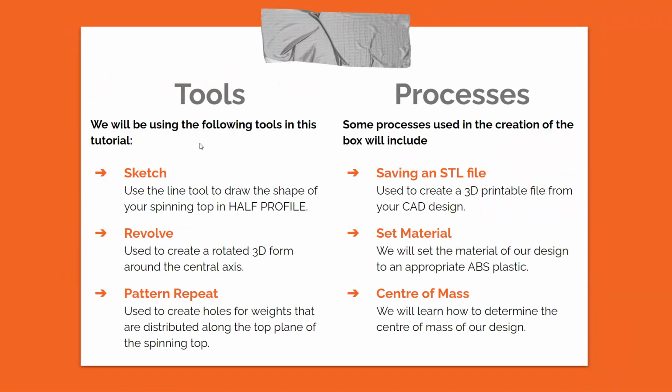So the tools we'll be using will be the sketch tool, the revolve tool, and the pattern repeat. We'll be using the pattern repeat to make holes for our weights, okay? We'll be building a little bit of tolerance into those holes.